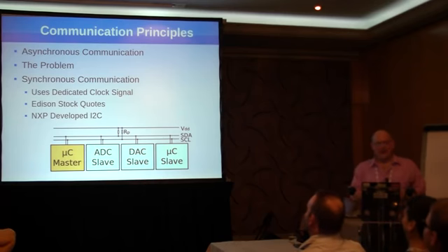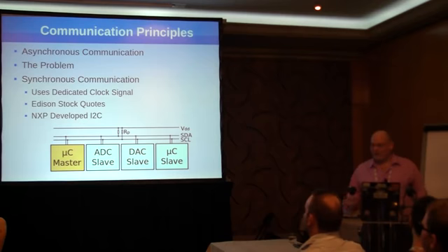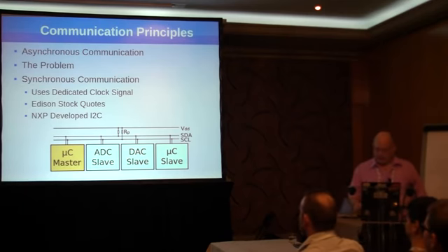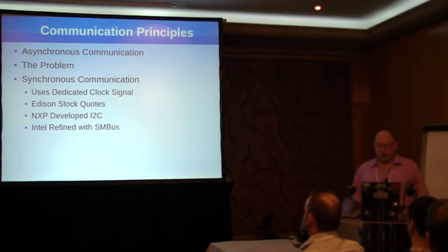So that brings us to I2C, which can be pronounced several different ways, but that's a particular phrase that I like to use. It was developed by NXP to allow for a wide range of small, simple devices to be connected to the controller or processor that they were working with. It allows you to connect multiple units on the same bus. Intel took the I2C specification and refined it for their own needs and actually refers to it as SMBus instead. Virtually every laptop and netbook out there has some sort of SMBus functionality inside of the device.